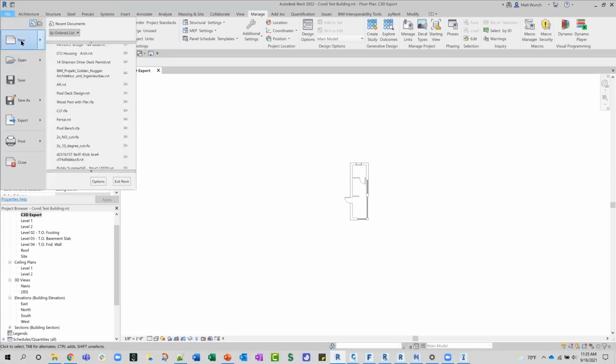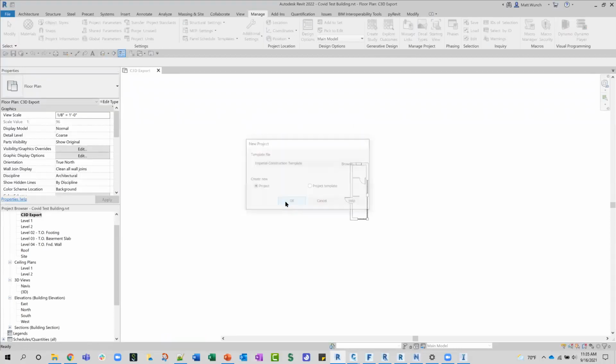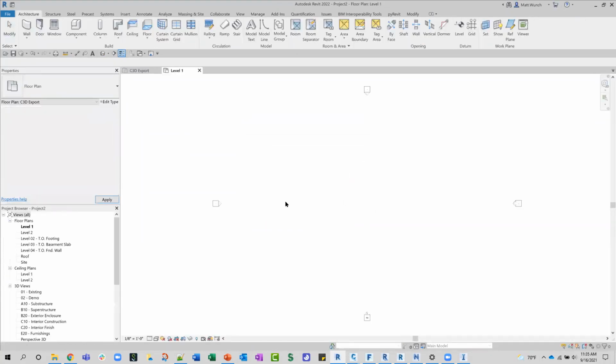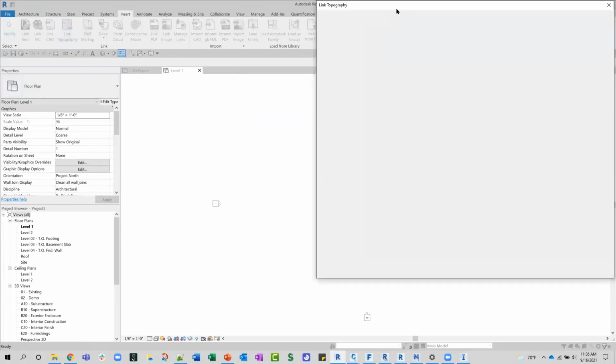Let's go with the first one, which is we've got nothing modeled in Revit whatsoever. Brand new project, never been touched, nothing's ever been done to it before. So on the Insert tab, we want to link the topo from that cloud project. And depending on the number of cloud projects you have or are associated with, and the number of hubs and projects, this may take a little while to spin up.